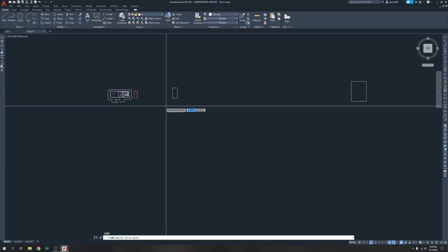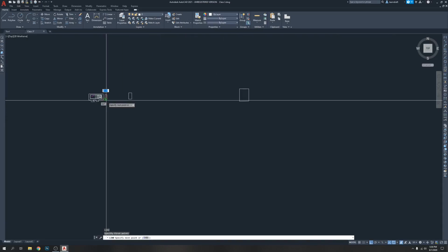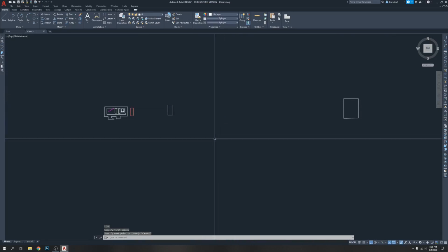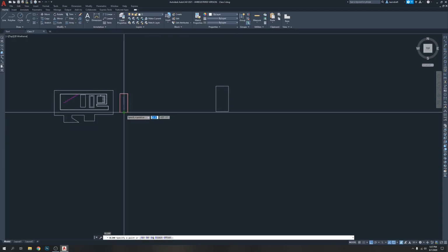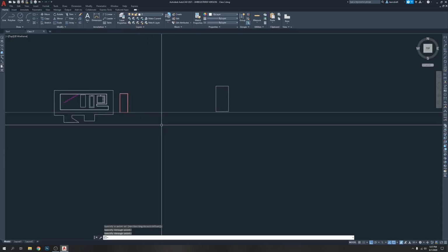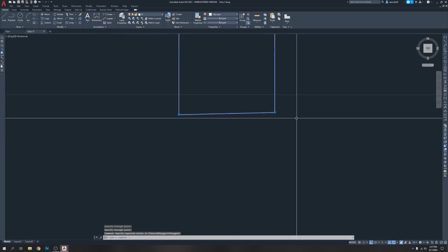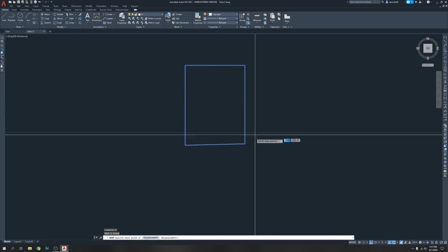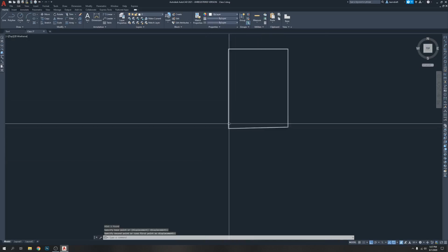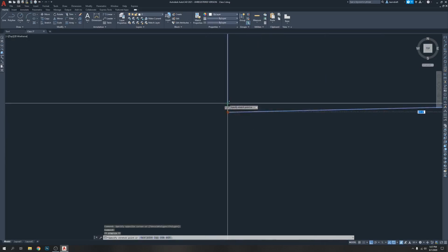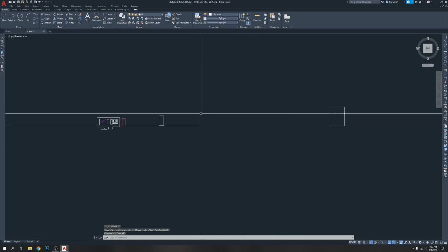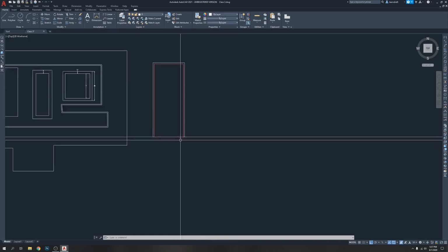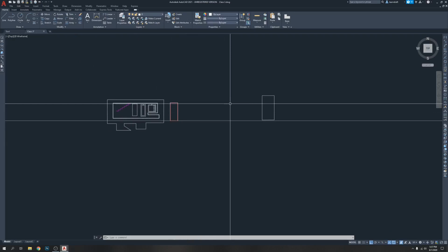Now if you draw a line, L, enter, then go zoom in, then click, then you bring it there. This is still time consuming. So what are you gonna do? Press XL, enter, just click here and click there, enter. So this line is aligned with this. Now you're gonna go there, just move this one, but the move command we did not cover yet, but I'm showing you if you can catch. Okay, so this one is not perfect. I'm gonna click it here, push it there, it's gonna be perfect now. See, and most of the time you need this line. You can trim it, you can keep it, you can delete it. So we draw with this line. So this one was XL.